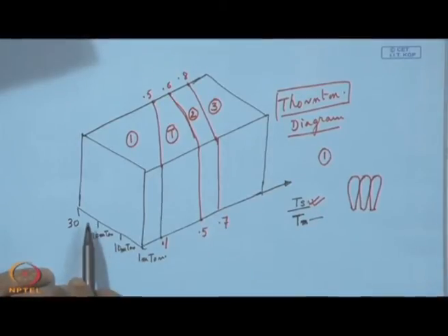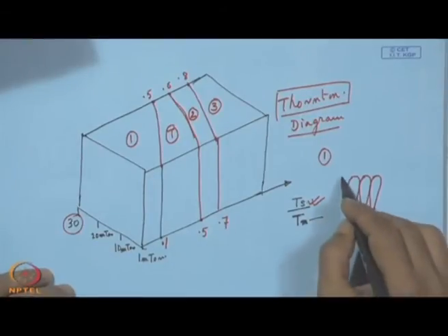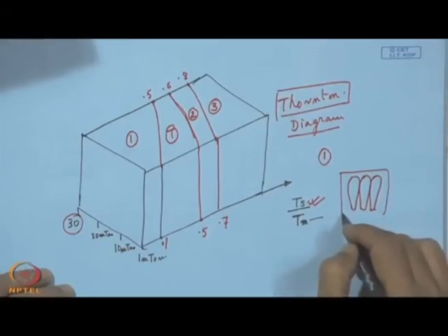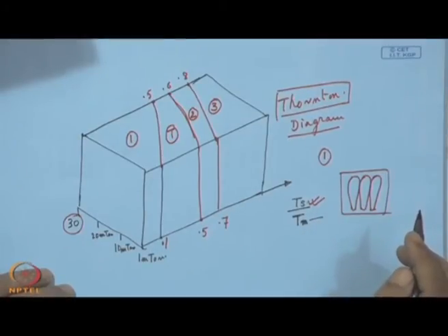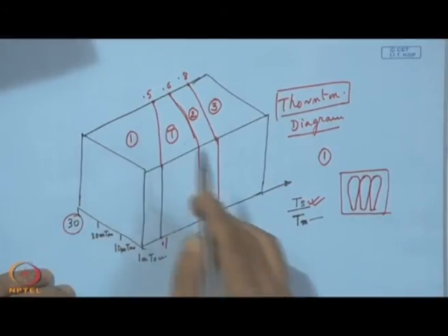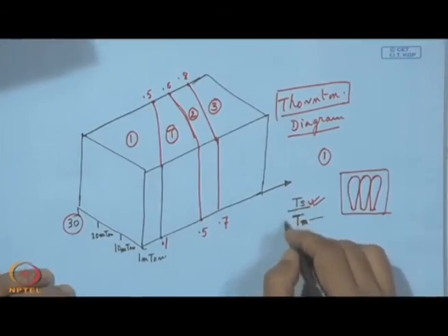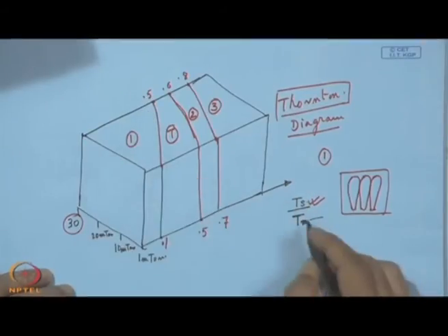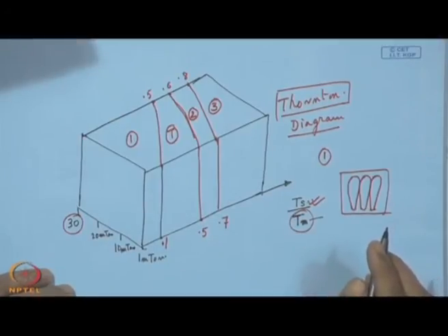We can have high pressure, and we can ignite the discharge, that means initiate the sputtering, with much ease, but in that case we will always be left with such an undesirable structure or growth architecture of the coating, and that can prevail even if we increase the substrate temperature to 50% of that of the cathode material or the target material.